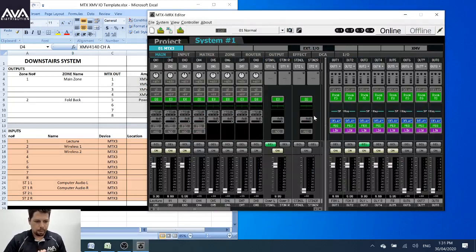All right, cool. So you might have a bunch of presets. I mean, the world's your oyster in this regard. You can literally create different system settings, and you can recall that with a button on the digital control panel. You can put it on the scheduler to say, at this time I want this preset to be recalled. I like to have a system default preset scheduled, say, every morning. So if staff or anyone messes with the system and changes something, every morning the MTX is going to revert back to its initial setup.